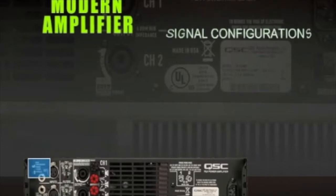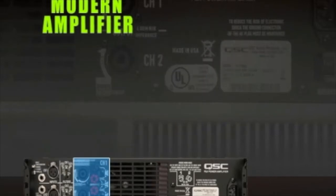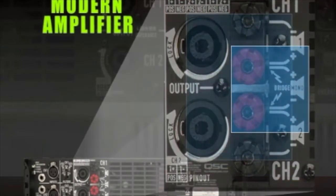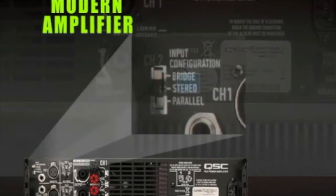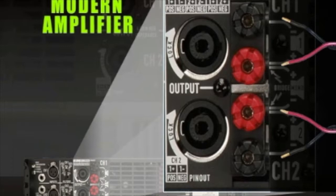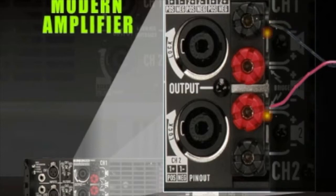Most modern amplifier designs incorporate several operating modes that manipulate the input and output signal configurations. The two input configurations are stereo and parallel mono, and the output configurations are stereo and bridged mono. These settings are typically selected via switches on the rear of the amplifier. Attention should be paid to proper wiring of both the input and output connections. Improper wiring can cause severe damage.